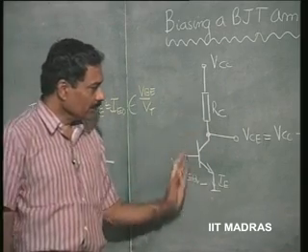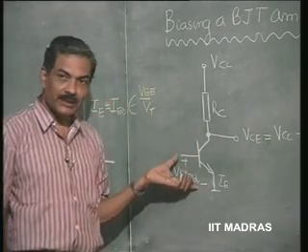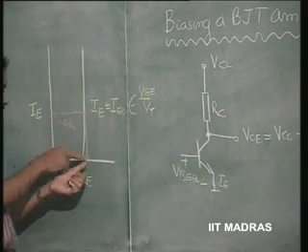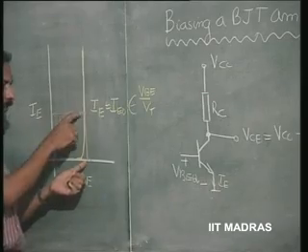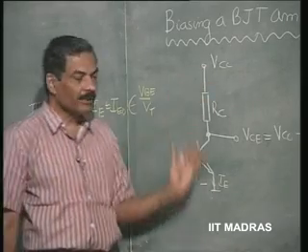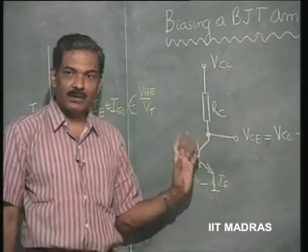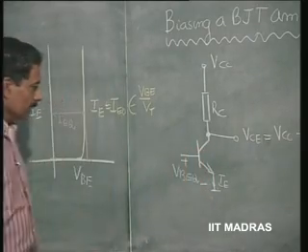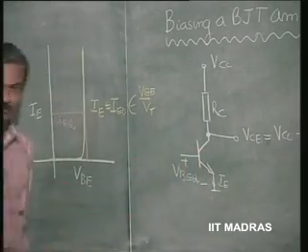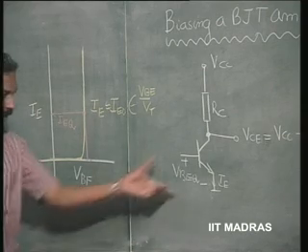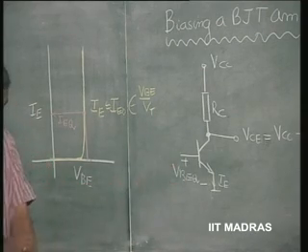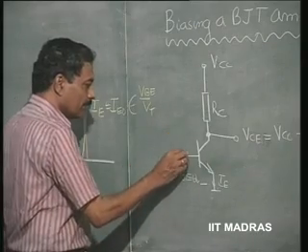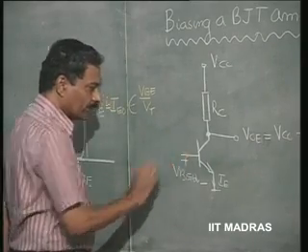So, for any voltage which is greater than that exactly specified voltage here for 1 milliampere, this may go to saturation. It will no longer work in the active region. So, this way of biasing, fixing this voltage here, is no good.